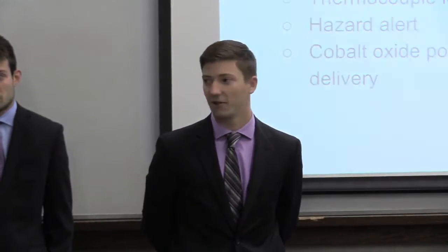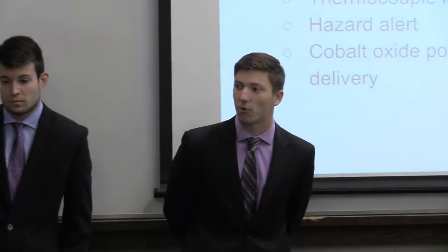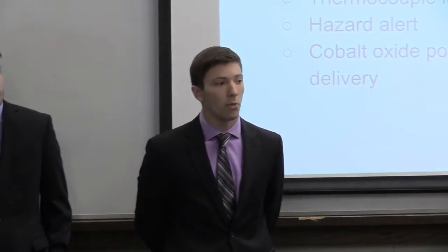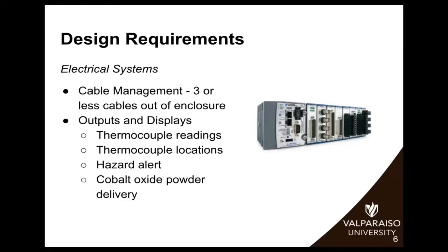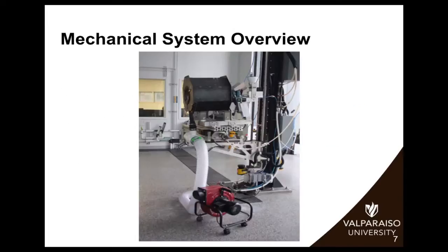Onto the electrical design requirements, we needed to have at most 3 cables running between our enclosure and the user. We also needed to output the readings of the thermocouples that are at least plus or minus 10 degrees C in accuracy, as well as store that data. We needed to specify the locations, have a hazard alert system, as well as efficiently deliver particles.